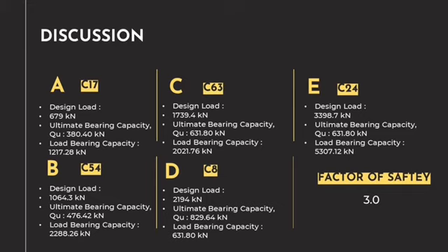Lastly, the soil condition for this project is mostly sand, so to increase the foundation strength, we suggest building a deep foundation from piles because we assume it has weak soil properties.